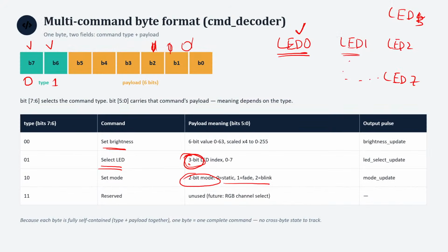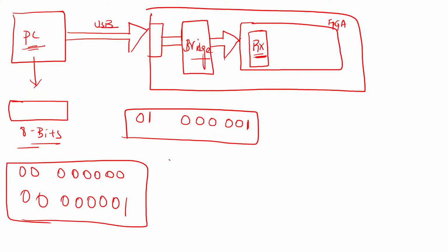Now, let's say I'm going to decide the brightness of my LED depending upon the duty cycle of my voltage. If I want 0% LED brightness, then I make my duty cycle equal to 0, which means my voltage is not given at all.